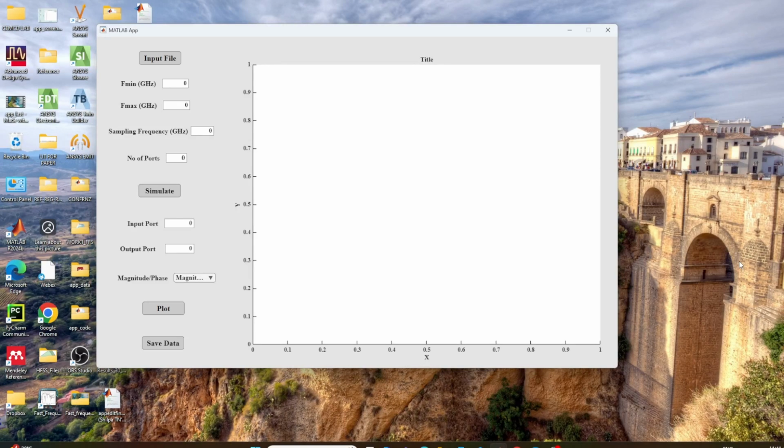In this video I am going to explain the adaptive frequency sweep application that we have developed for Matlab RF PCB Toolbox. The adaptive frequency sweep technique is based on approximation of a mathematical function, which adaptively chooses the simulation points depending upon the specified error criteria. This method can be used to reduce the computational time without any compromise in accuracy. In this work we have incorporated Davide Predovera's minimal sampling algorithm for adaptive frequency sweeping in electromagnetic simulation.